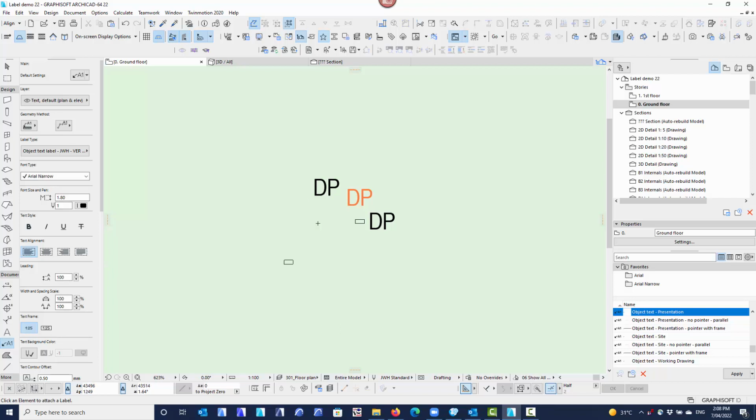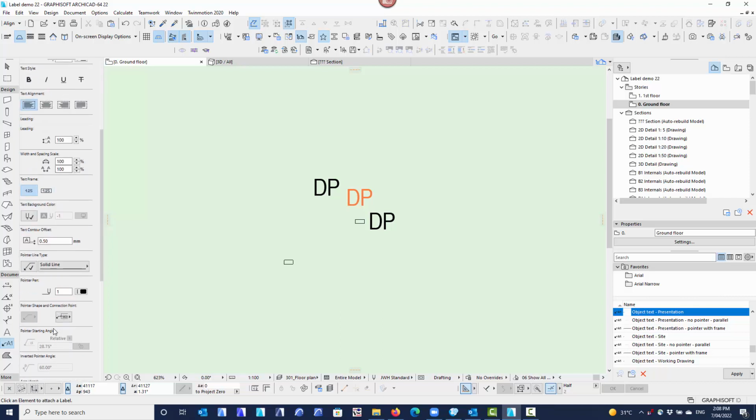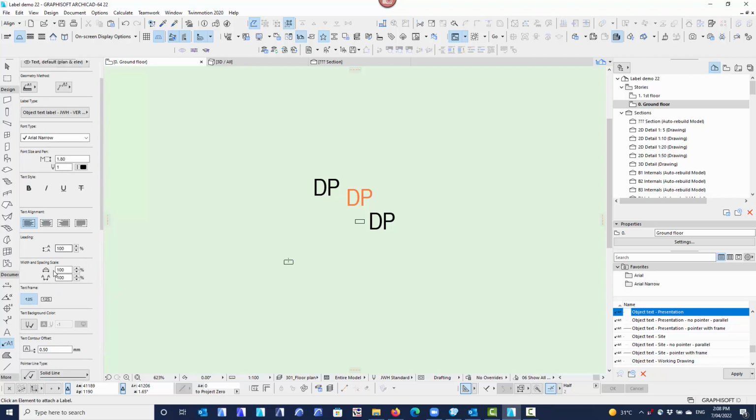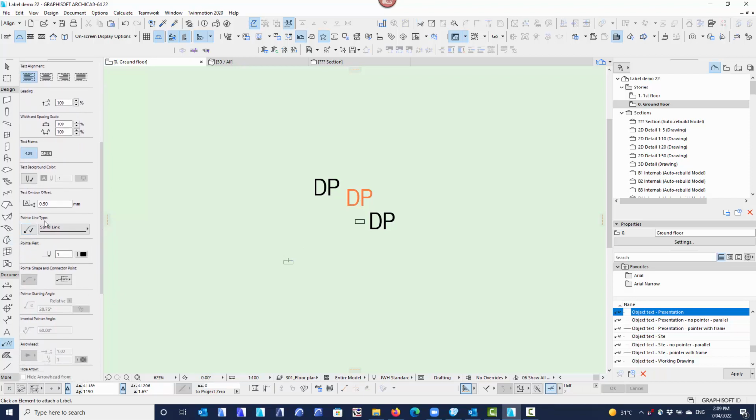I know it's a downpipe, so if you've got an existing label for downpipes and you want to label downpipes, you can just alt click one and you know that it's getting all the correct information for that label. But what's important too is it's also setting up things like the width of the label. It's not actually the marker size that it uses. If you're doing an auto text label, the width of the label is that. This is controlled through the object script. Basically what will have happened is it's turned the arrow pointer off and set the width.